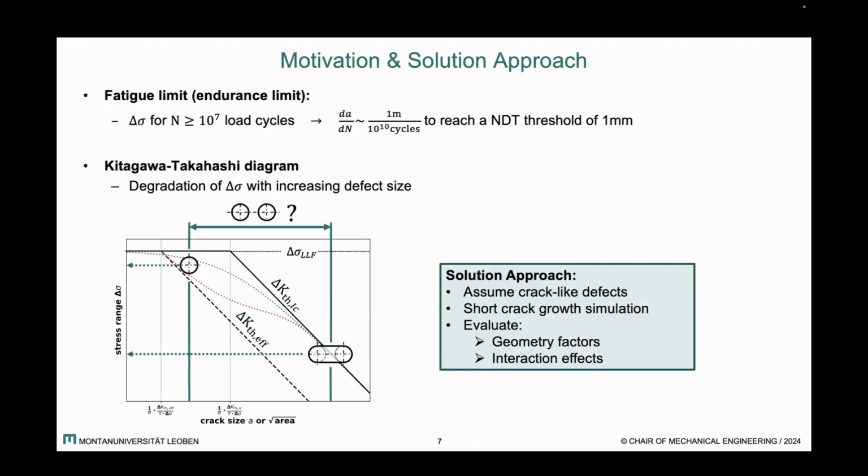That's a problem that has been investigated in numerous ways, but my approach would be to assume crack-like defects, perform a short crack growth simulation and extract geometry factors and interaction effects onto the fatigue limit.